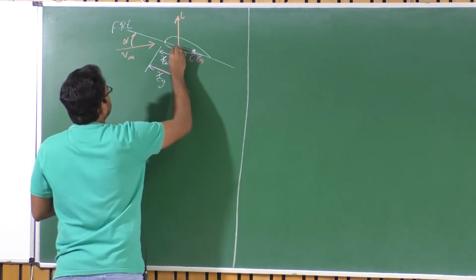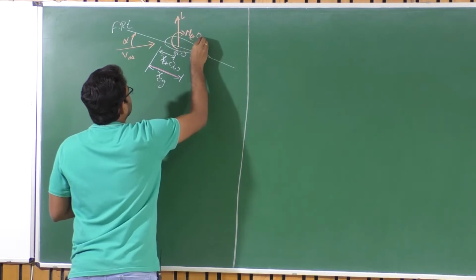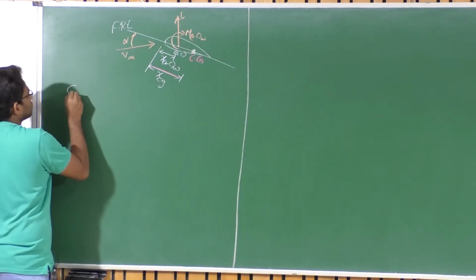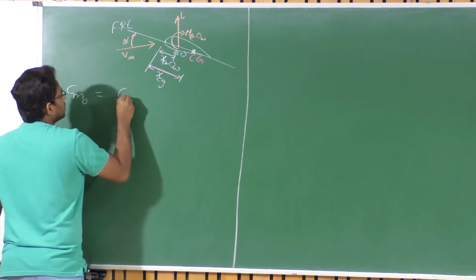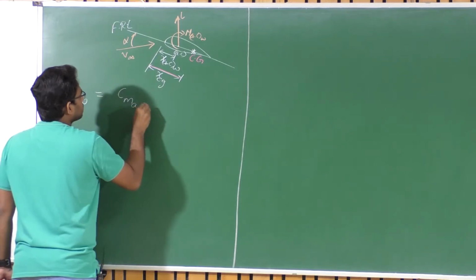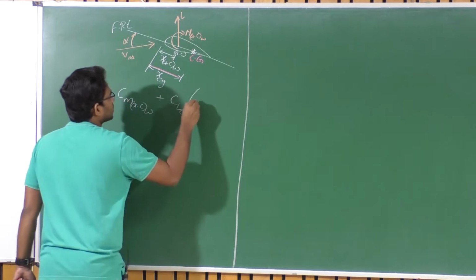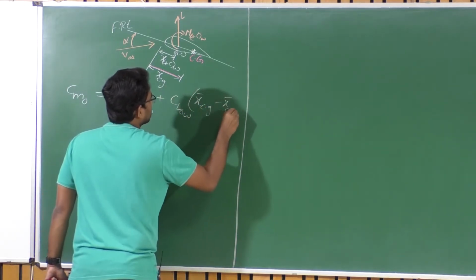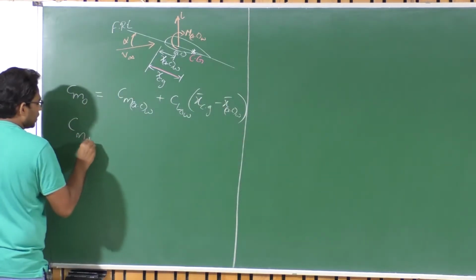and we have the moment about the aerodynamic center of the wing. So, what we have derived is Cm naught of this aircraft has to be Cm AC of the wing plus CL naught of the wing times x bar CG minus x bar AC of wing, and at the same time we also looked at the Cm alpha.